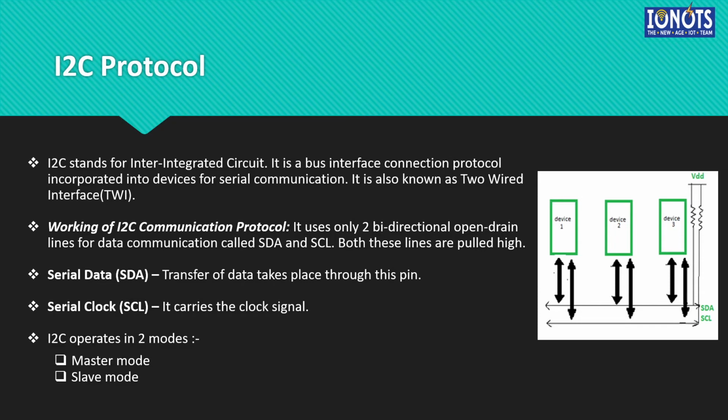Now there is another special feature that we need to look into, which are the repeated start conditions. Between each start and stop condition bus pair, the bus is considered as busy and no master can take control of the bus. If the master tries to initiate a new transfer and does not want to release the bus before starting the new transfer, it issues a new start condition. It is called a repeated start condition.